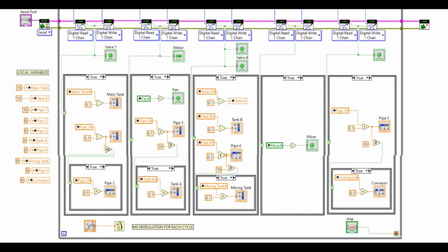You cannot see it here in the video, but the assignation of the Arduino pins are above the link's terminals. Pins from number 2 to number 11 were used, and even numbers were used for read and odd for write.